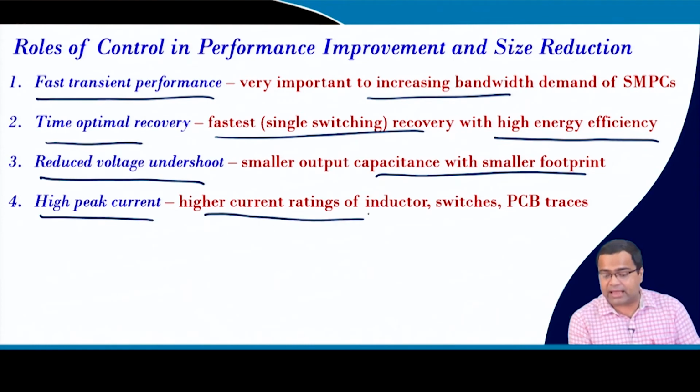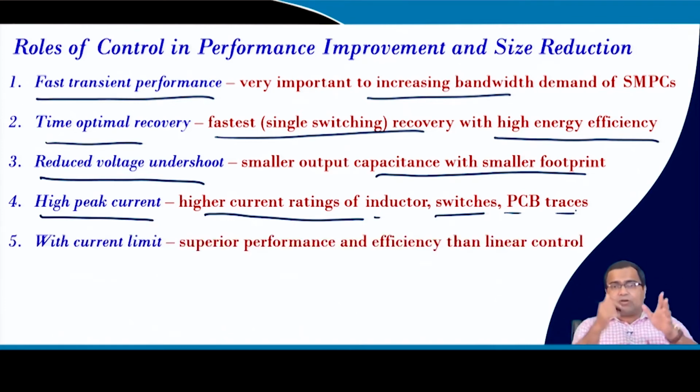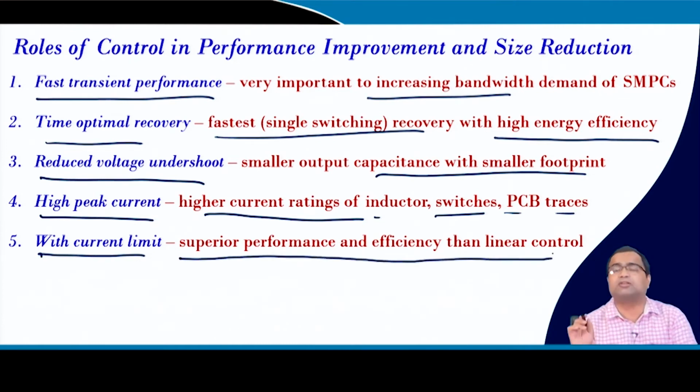So, that requires a higher current rating inductor and switches, and it can also increase the PCB trace current rating, as well as, if you go for an IC, the bond pad that has to carry the current, right. But we can incorporate current ripple, and we can also get much superior performance and efficiency than linear control even